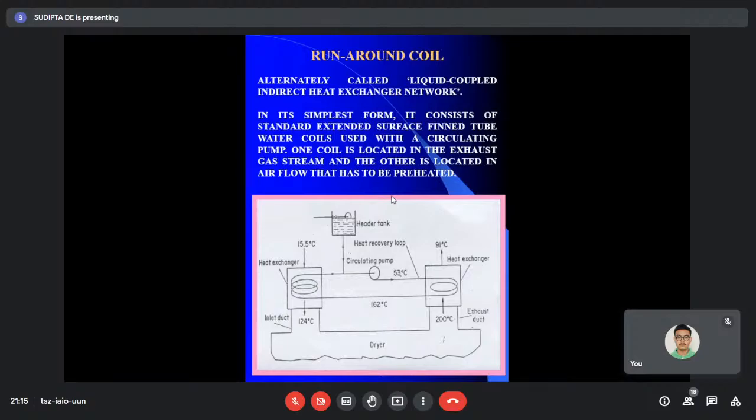Now, if the entire cooling process is for a 40 to 20 degrees Celsius change, then the corresponding electricity requirement or AC power consumption will be very high. What you can do, at least partially, is reduce it by exchanging heat between the cooled air rejected from the confined space and the fresh incoming air from the atmosphere. This heat transfer may not always be possible side by side because the two ducts may not be adjacent. So to make this heat transfer, we use this run around coil.